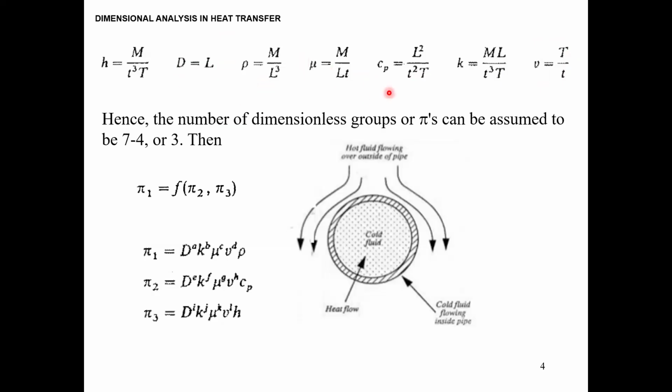You are all grad students. From here you should be able to pick up and work it out. And dimensional analysis starts with this step. The next step is trying to express your dimensionless groups in terms of the different variables. Since three groups are involved, we pick any three variables and distribute them across, and the remaining variables we keep as a constant across these three groups.